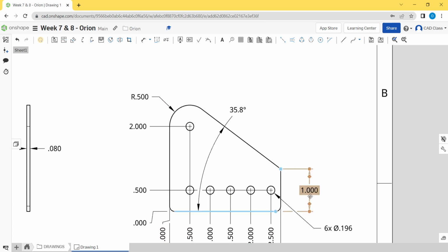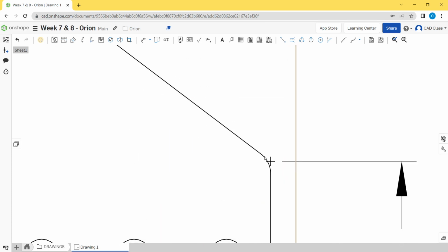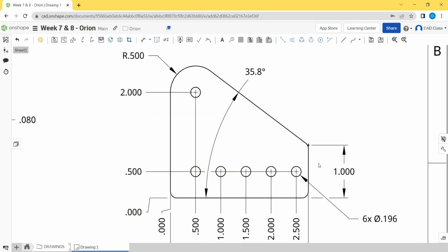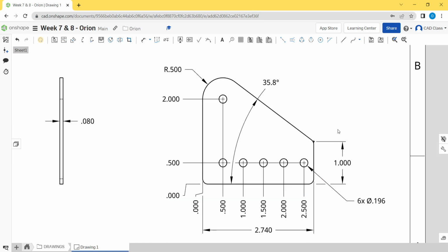And so you could manufacture it using this 1 inch dimension, and then you would come in and add these radiuses after the fact, possibly just with a sander or some sort of deburring tool or a file. You wouldn't necessarily machine these rounded corners in, because there's no real easy way to do that on a manual mill or something.